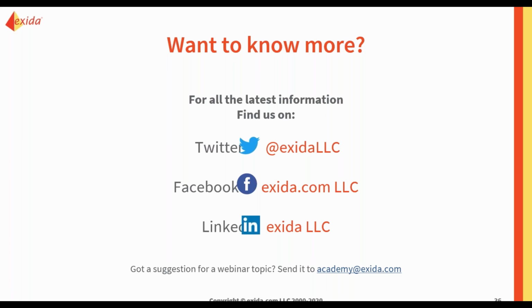Or you can also always have the FMEDA redone. Not necessarily go through the whole certification thing, but maybe just get the FMEDA and realistic failure rates. So you do have some options. They're not necessarily the easiest or best, because it would be much better if you could just get a certificate with what you liked on it, but you do have some options, and hopefully we can help you. And if not, just at least using that reality check or that SIL Safe Data can help you just know when to accept it or when not to.